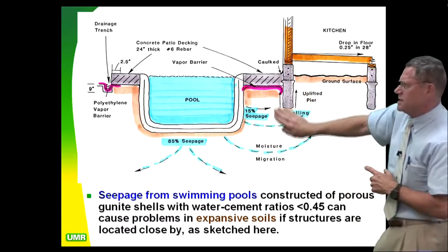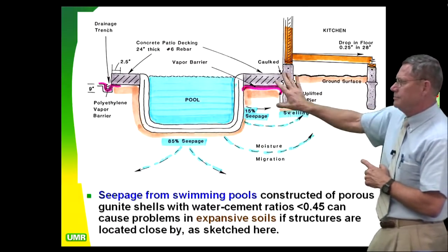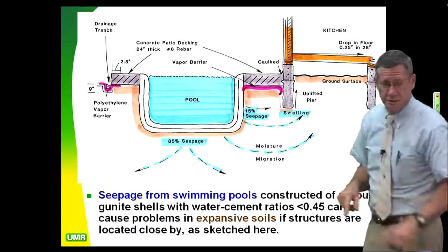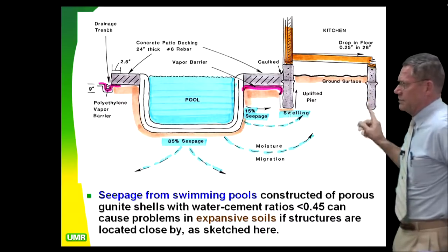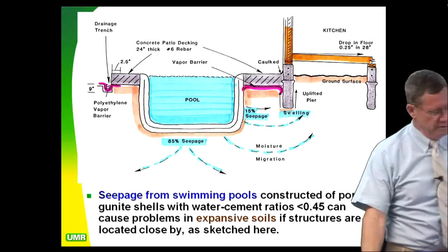And it was just this outside line of stub piers, these are only 42 inches deep, that lifted up. And that was enough to drive him nuts because his bowling ball was rolling across the kitchen. The kitchen was in the back of the house. This pier did not go deep enough to get lifted. So it's differential heave, once again, that drives you nuts.